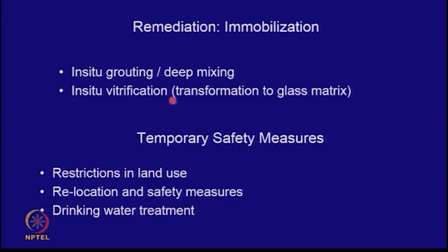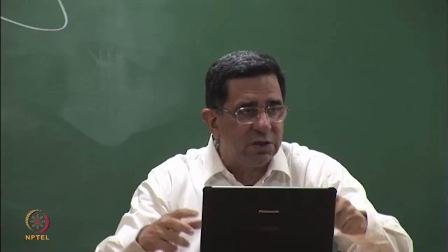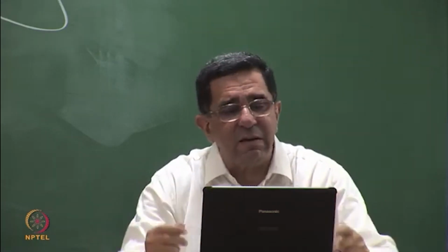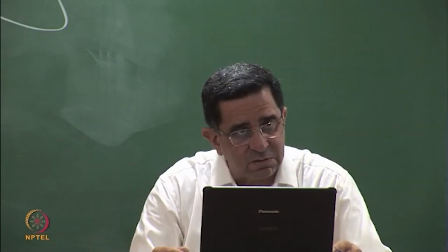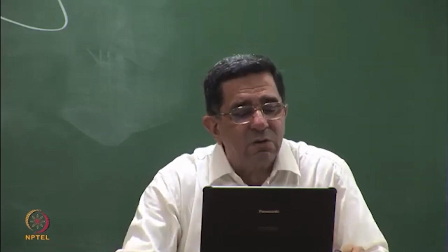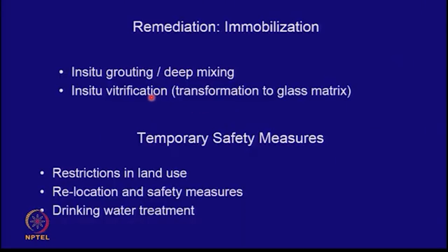Of course, the ultimate is in situ vitrification, not yet a significant reality. But if you can, either through high heat or through high voltage, convert the matrix into a glassy substance which will entrap all the contaminants, then that is also a technique that we would like to adopt. That means transform the contaminated soil into a glassy, amorphous matrix.